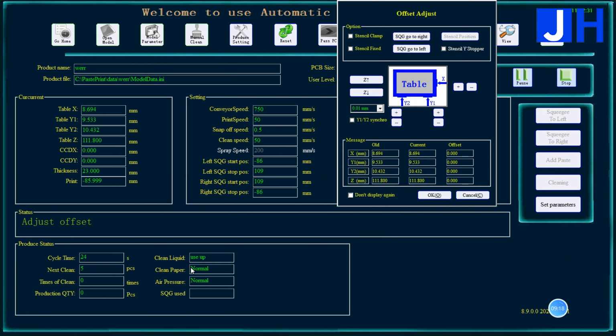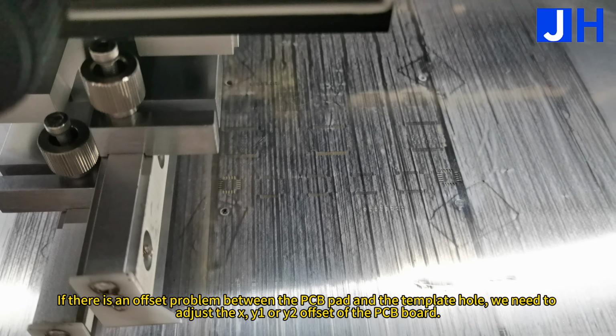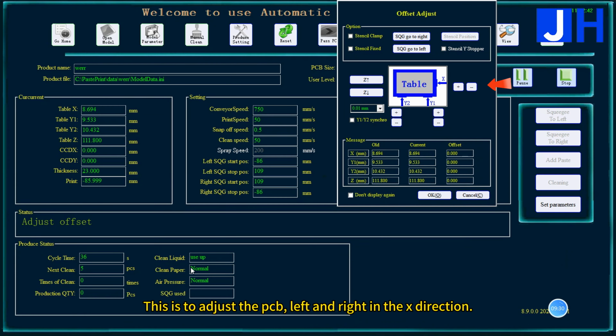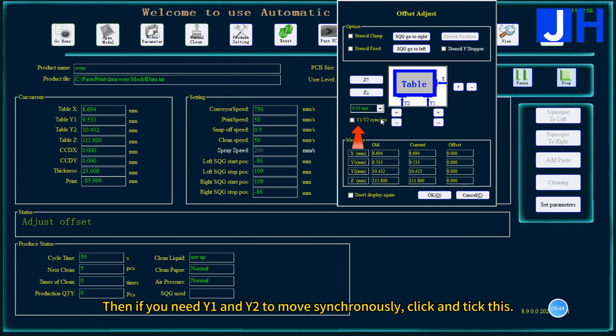Let's go check. If there is an offset problem between the PCB pad and the template hole, we need to adjust the X, Y1 or Y2 offset of the PCB board. This is to adjust the PCB, left and right in the X direction. If we need to debug the Y direction, we click Y1 or Y2, Y1 on the right and Y2 on the left. Then if you need Y1 and Y2 to move synchronously, click and tick this. If you click Sync, it is the overall Y direction movement.